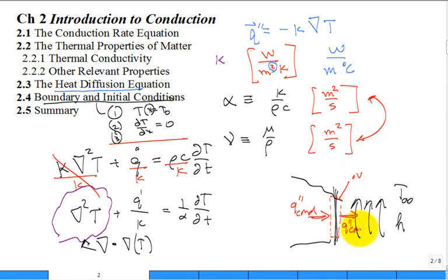convection flowing out. And because it's so thin, even if I have a transient problem, at any instant in time, what flows in from the left by conduction must flow out on the right by convection without any accumulation. It's so thin, there's no mass, no thermal capacity for heating up that surface.